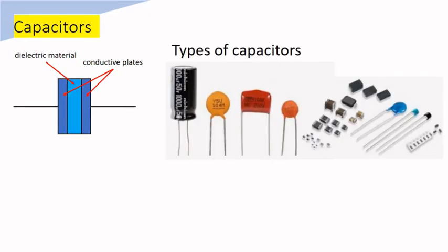There are many types of capacitors available in the market. For example, here we have an electrolytic capacitor, which has polarity that we need to be careful with in making the circuit connection. There is also the ceramic capacitor and the surface-mounted technology capacitor for the flat printed circuitry. Although the structure seems very simple, in actual design, it is not.